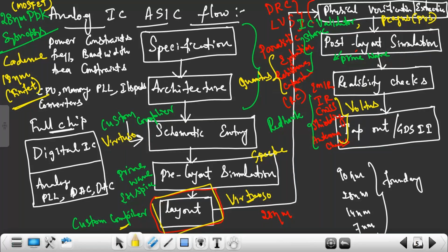Now you can start creating the libraries and cells, then draw the schematic, then the layout, then do parasitic extraction, then post layout simulation. For a few circuits I'll teach you all the steps from schematic capture to post layout simulation. But as a layout engineer, you will mainly focus on drawing the layout for the given schematic.